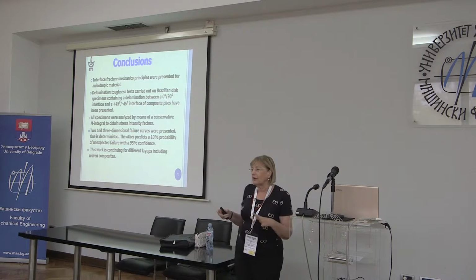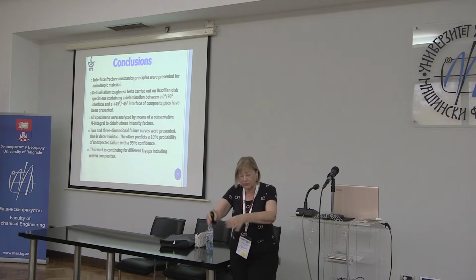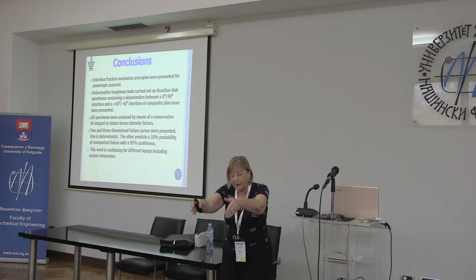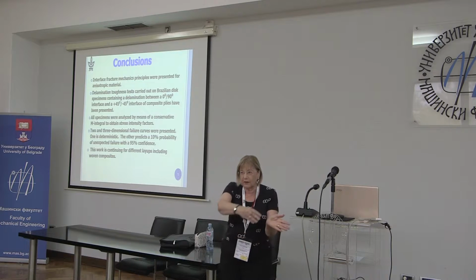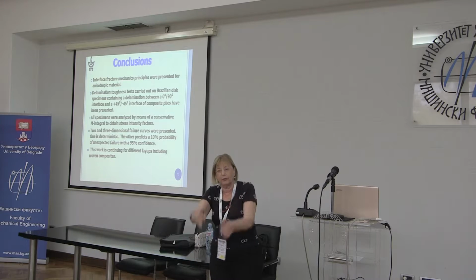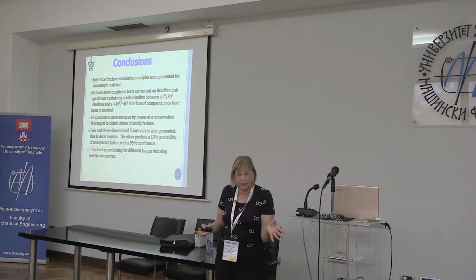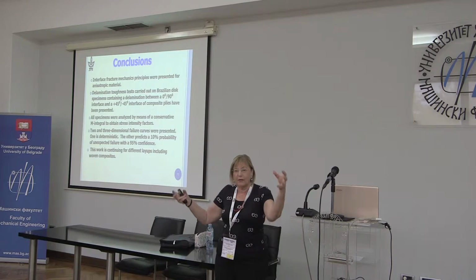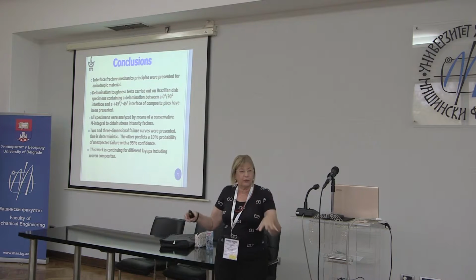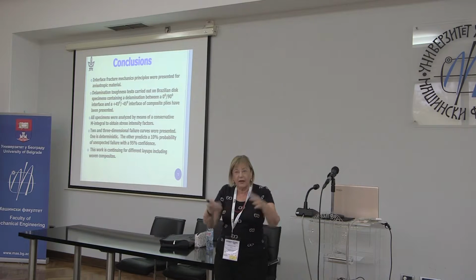And then the technician that's going to build some structure has instructions. I saw they had a whole big wing, and he lined them up in the 0 degree direction, then in the 90 direction, then in the plus 45, and the minus 45, and so on and so forth, until he had the layup that he was instructed to make. And then they take this part and they put it in an autoclave, at a certain temperature and pressure, and the epoxy melts, and then the plies glue together, and after a while, out comes your structure.